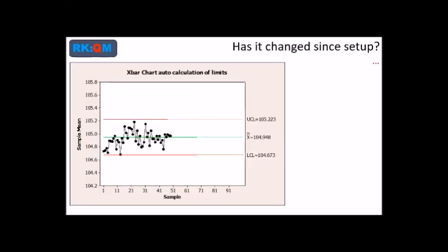One use of measurement is to produce the control chart, the X-bar chart, sometimes known as the Shewhart chart. We expect to see some variability in the process, and the control limits tell us what variability or fluctuation in the process we can reasonably expect to see. This visualization of the process means we shall not react without good reason. When measurements go outside the control limits, we can say with confidence that the process has changed and we must act. And here again, it has changed.